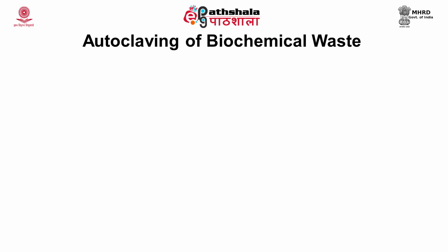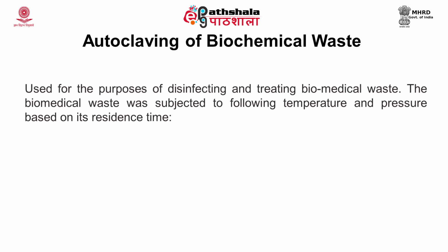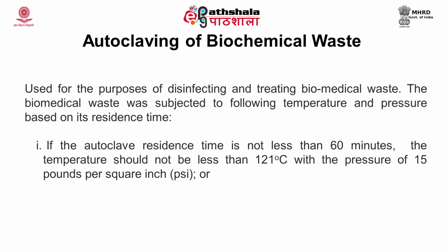The next type of treatment method is autoclaving. Autoclaving of biomedical waste is popularly practiced. It is used for disinfecting and treating biomedical waste. The biomedical waste is subjected to the following temperature and pressure based on its residence time. If the autoclave residence time is not less than 60 minutes, the temperature should not be less than 121 degrees Celsius with a pressure of 15 pounds per square inch, or psi.